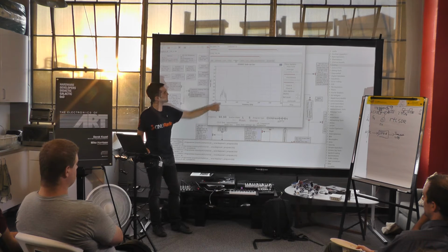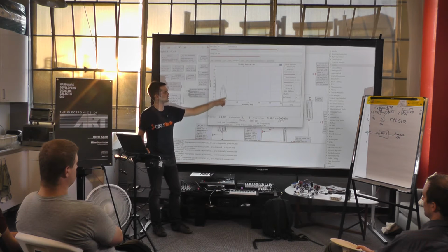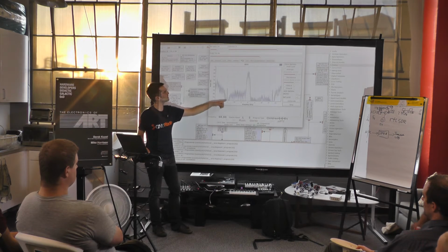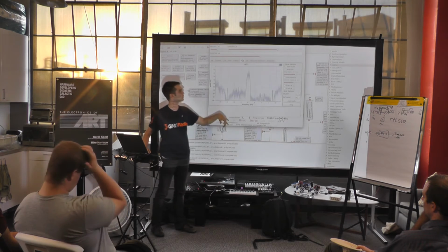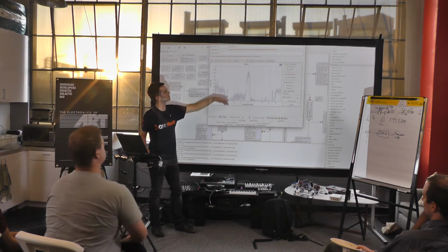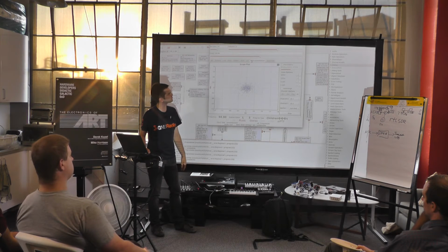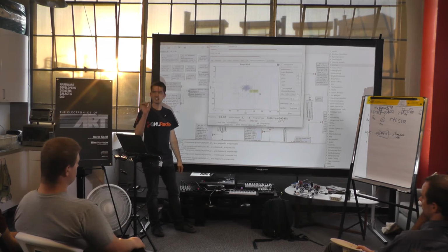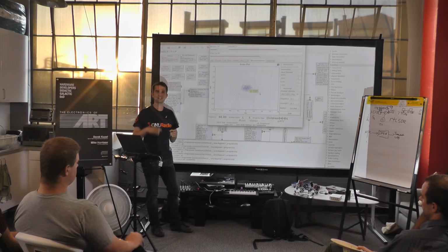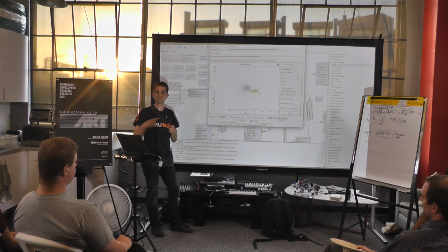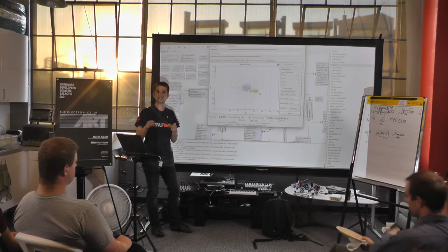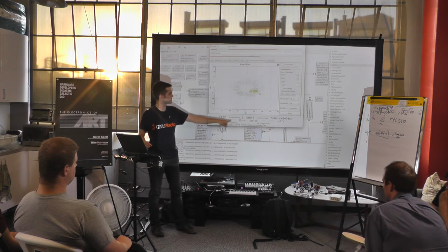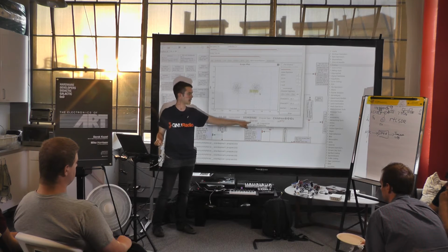Not very interesting. But here's our digital sideband suppressed carrier subcarrier. So this is the digital information being stored right here. And the RDS looking a bit on a wider spectrum. Left minus right. RDS constellation. RDS is the digital information that's being transmitted. It's the system of transmitting the digital information that decodes into the station information. So you can see that this is actually the decoded output here.